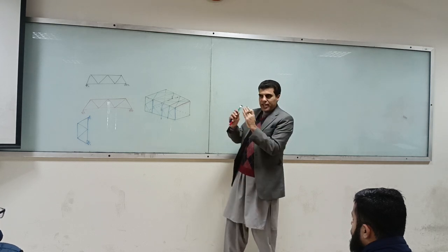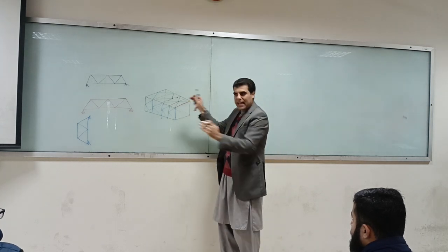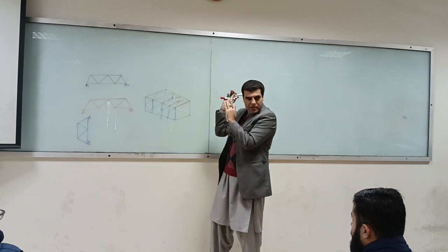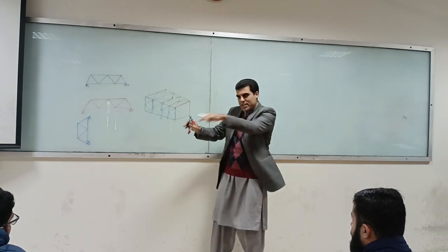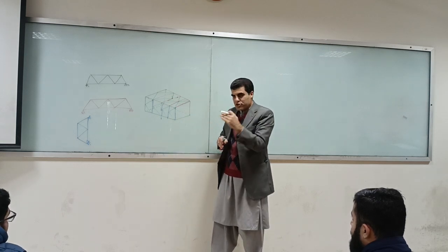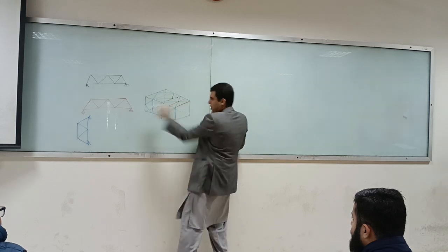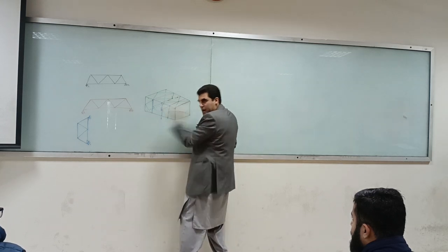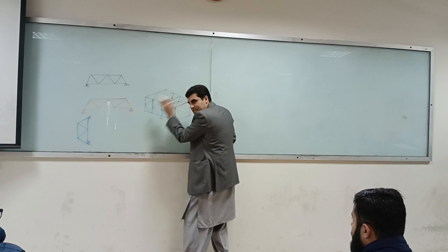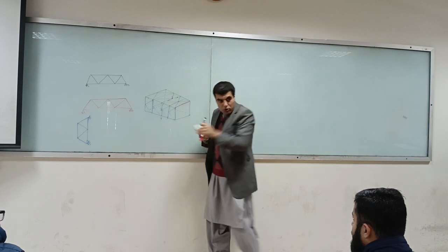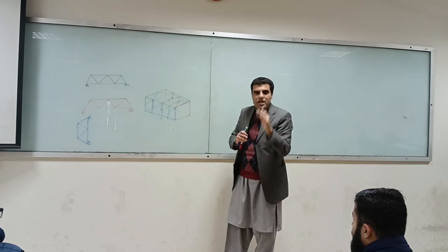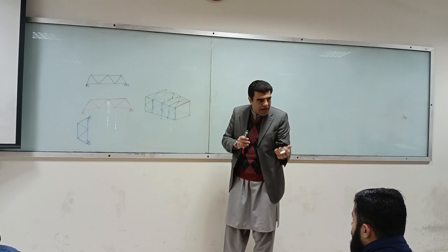Okay, so laterally you can have load in this direction. That can be wind load, that can be earthquake load, which is always horizontal, isn't it? So for example, if someone is shaking it in this direction, that load must also come to the ground. So you have to check whether you have provided proper load paths.